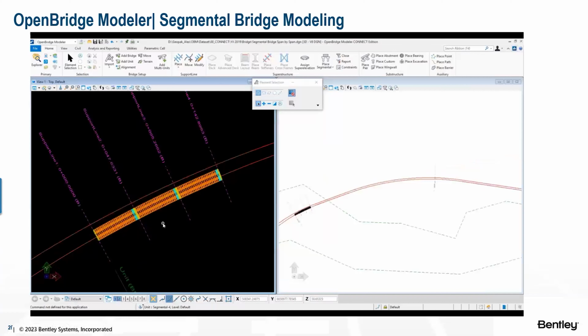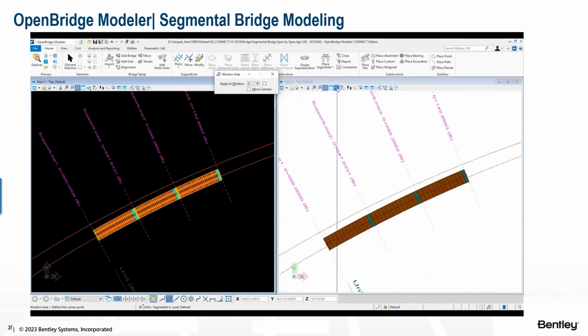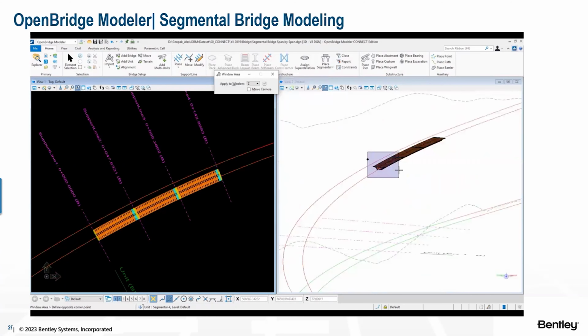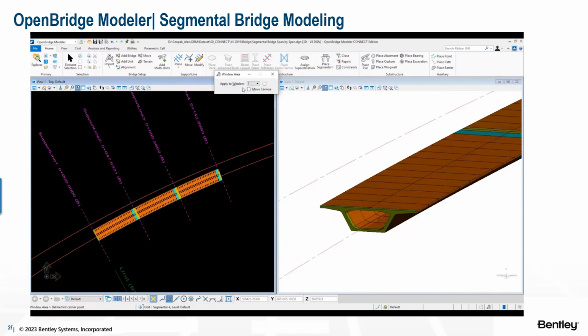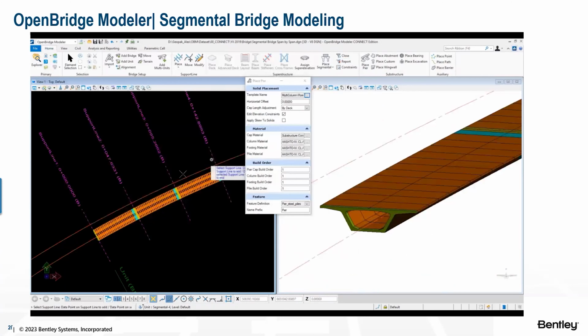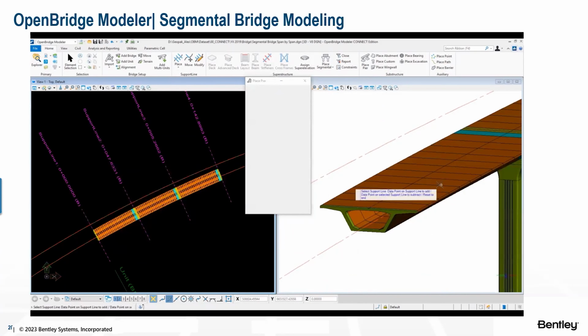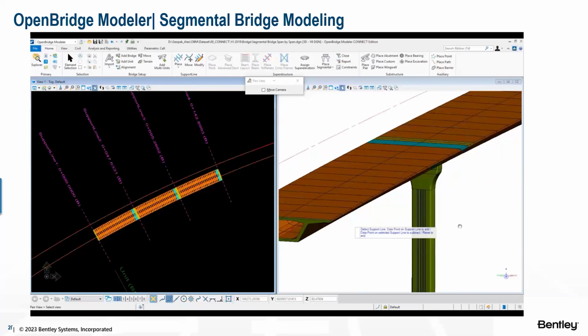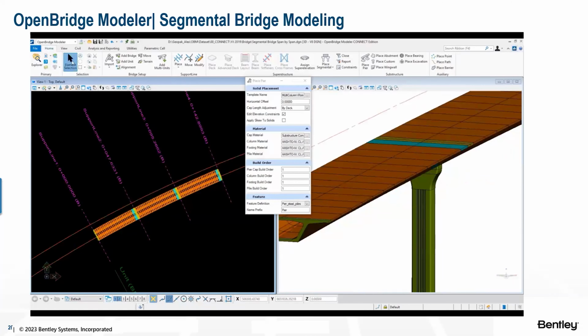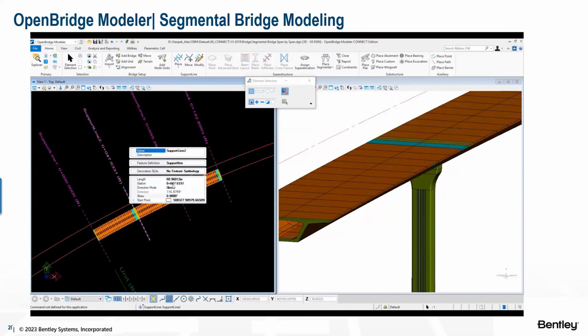We can, for instance, define, here it's span by span, so we can define what is the value between the segments on each pier, okay? So usually this is made in straight span and maybe for subway. In case of balanced cantilever also, and in curved bridge, what is interesting is that we can define exactly the position of the cross-section. It can be coded if we have precast segments, for instance, or it can be perpendicular to the alignment.